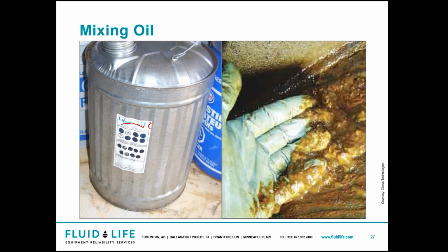The other thing with galvanized is galvanizing has zinc in it, and the oil can actually draw the zinc out of the coating, and then you're throwing out your additives. So zinc is part of an antioxidant package, and so if there's zinc, it's going to try to pull that out as well. The one on the right, that could be two mixed oils, or it could be a mixed oil and grease.